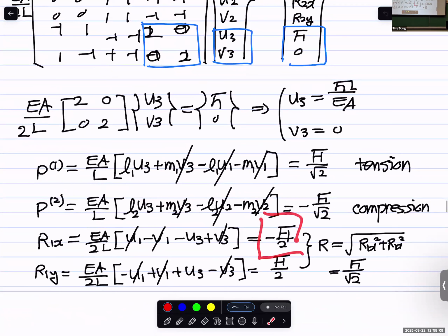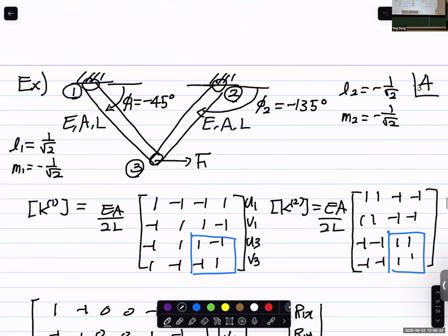Component, there's a negative sign, there's a positive sign. In the x direction, it's a negative sign, and in the y direction, it's a positive sign. And we talk about the reaction force as one type of external force. The sign always follows the coordinates. So we know that it basically means that the y component is in this direction, the x component is in this direction. And the square root of something is always positive, but component-wise, you know the direction, right?